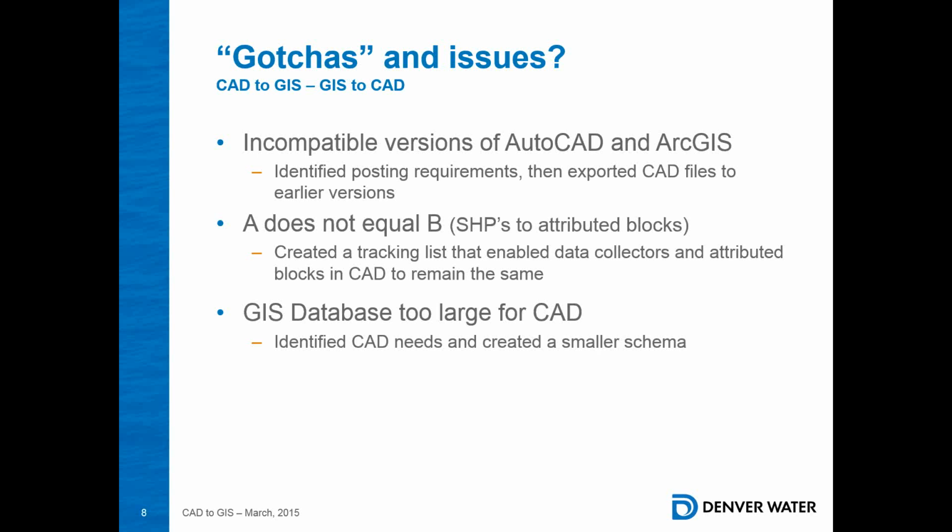Yeah, exactly right. And it will crash. So that's what Sandy was mentioning: you don't want to leave those connections on all the time and running inside your template, because we found that any time Esri's database locked up, all the CAD apps would start to crash. So that's definitely one of the big gotchas that took us a while to figure out. It seemed unstable, but we realized it was user error. Don't know about that. It was all my fault.